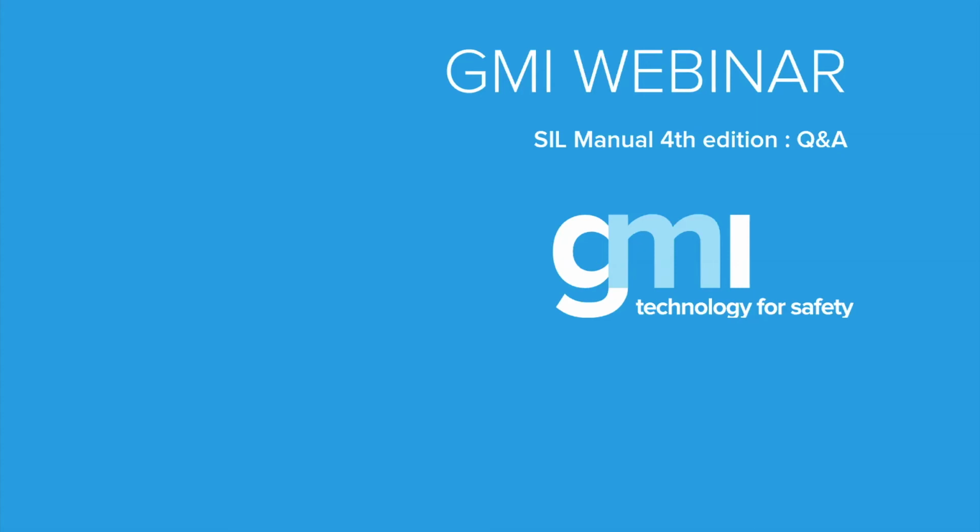As I'm trying to answer this live, I would say your understanding is correct. We have many different certifications, especially for safety. Now let us stick to the webinar topic, which is the SIS. For a safety instrumented system, when you are buying devices, I personally would say try to find devices which are compatible with 61508, and most likely the vendors will give you certificates stating that they are compliant to 61508.